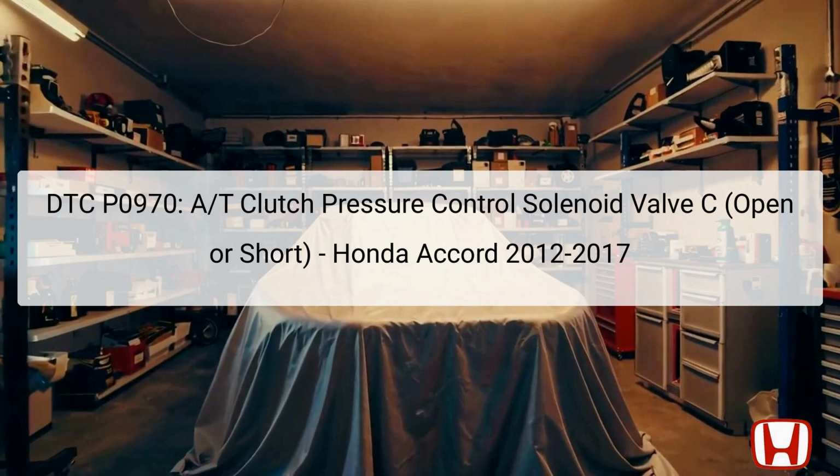This presentation addresses the diagnostic trouble code P0970, which indicates an issue with the AT clutch pressure control solenoid valve C in the Honda Accord models from 2012 to 2017. The DTC signifies that there is an open circuit or a short in the electrical system related to this specific solenoid valve, and it prevents the transmission from shifting to any gear other than first, second, or fifth gear due to a fail-safe feature designed to protect the transmission.